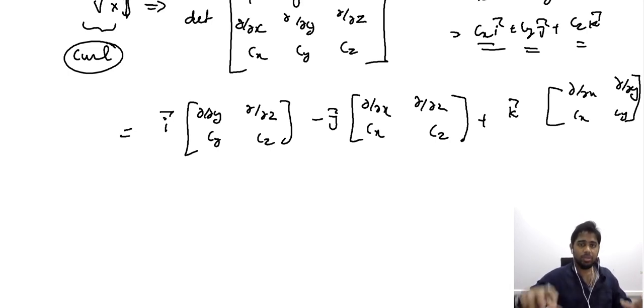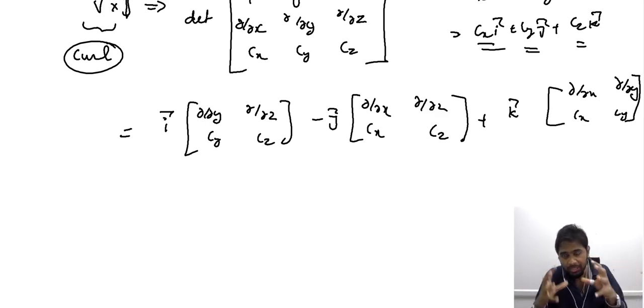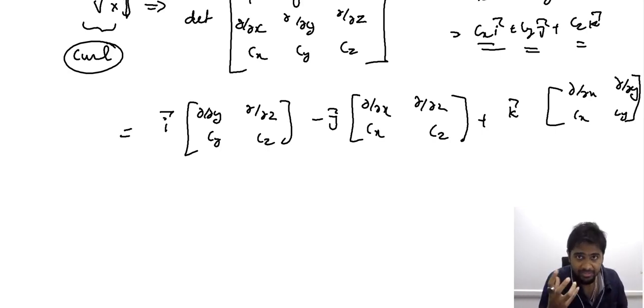Even though in the context of divergence or Fick's laws the curl does not play an integral role, it does play a role when you are modeling a system as a phase transformation wherein the liquid state plays a vital role. For instance, in solidification, the two phases are the solid phase and the liquid phase. It is not necessary that the liquid phase is static. When the liquid phase is dynamic, and a solidification is occurring in the midst of this dynamic liquid phase, then the curl of the flux plays a vital role.